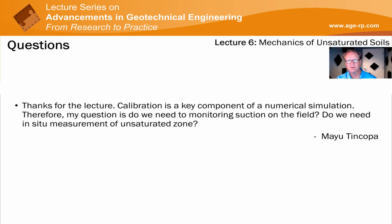But if you have a large unsaturated zone, maybe a way to do this is through back analysis: model it and find out what the potential influence is if you include soil suctions or you don't include soil suctions in your numerical model. You should be able to see if that makes a 5% or a 10% or a 25% difference in your factor of safety calculation. And then you can use the modeling to guide how important it is to model your soil suctions in the unsaturated zone. Maybe that's a way of approaching it.